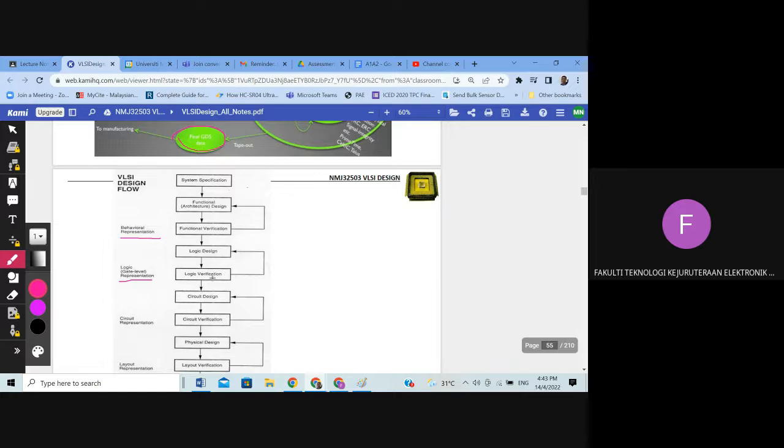And that's why a synthesizable behavioral design is very important. You need to write synthesizable code. Some code cannot be translated to equivalent hardware. That's what we call non-synthesizable. When the design is non-synthesizable, in terms of logic synthesis, some of the logic gates might not be inferred, and that will cause a problem. That's why we need to do verification again.